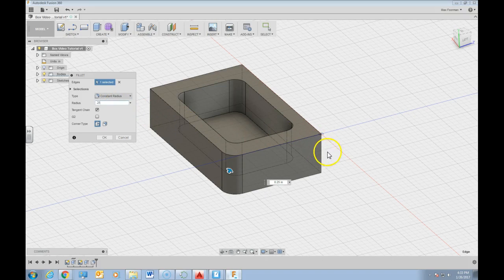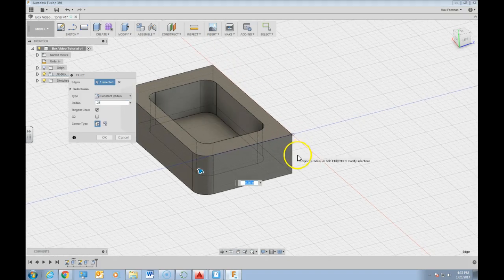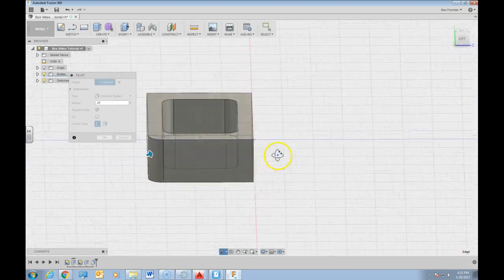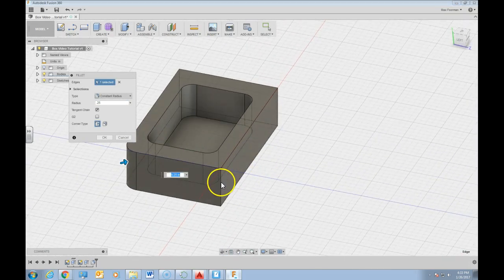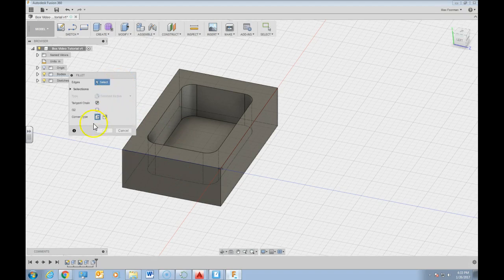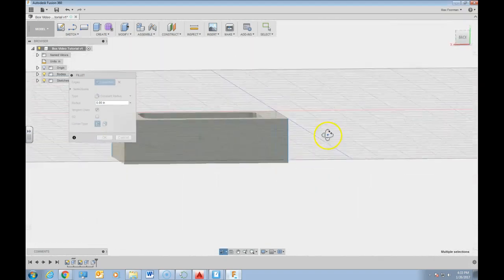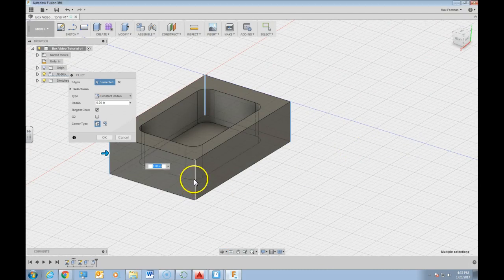And then I come back, and then it is challenging here. I haven't quite figured this out in Fusion 360 yet. It gets a little challenging in that now I've selected one corner radius, one there, and then it doesn't allow me to select any more. So just erase that back there, then there. So you have to kind of do this in order. I haven't quite figured that out in Fusion 360 yet. Not my favorite thing about it, but now we're going to type this in as 0.250.